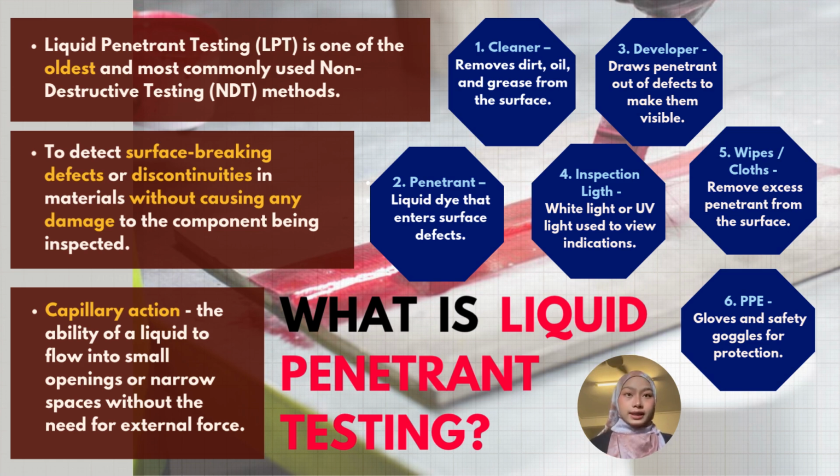For large-scale manufacturing, an automated stationary line with a large deep tank and drying oven is used. The inspection stage also requires specialized equipment such as UV-A LED lamps for fluorescent dyes and TAM calibration panels to verify the testing chemicals are working correctly.